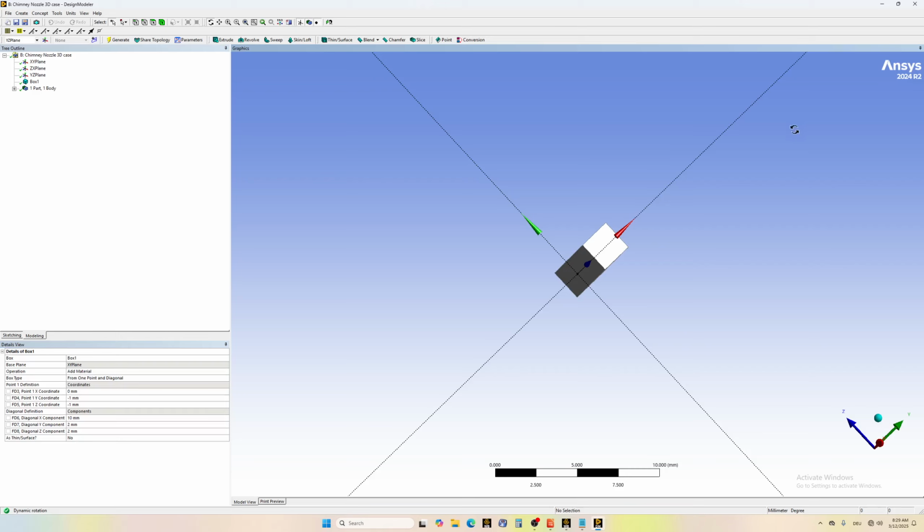Of course, don't put it ridiculously far away. You have to go in steps. Put it first close and after you run the simulation, check the density profile. If it's not flat enough, or if the shape is not as you want, then you move it farther and farther away, until you reach a point where you are satisfied with the results.